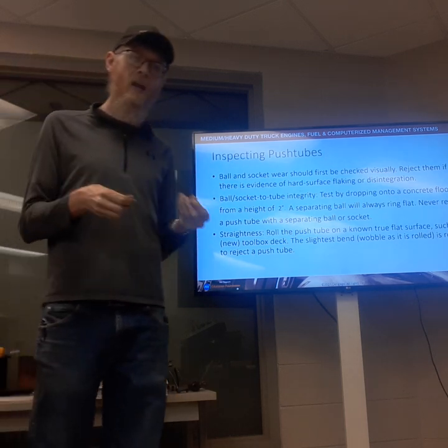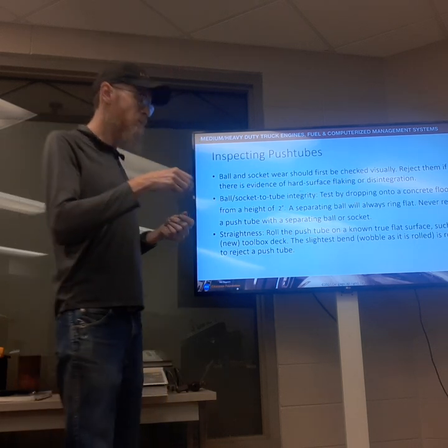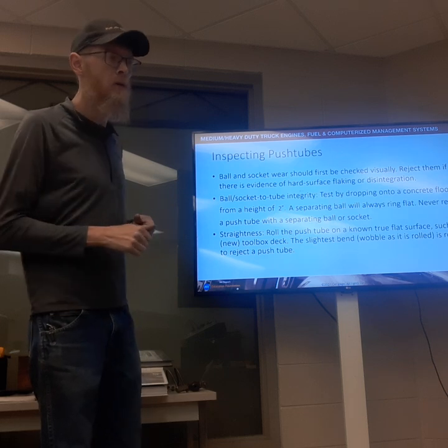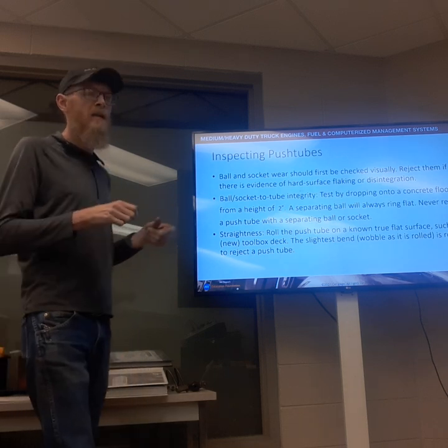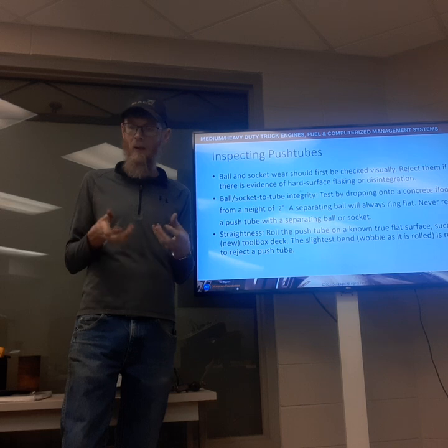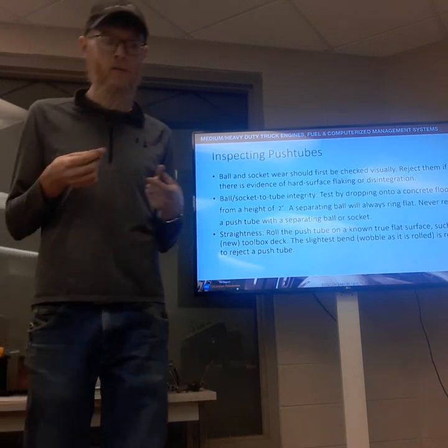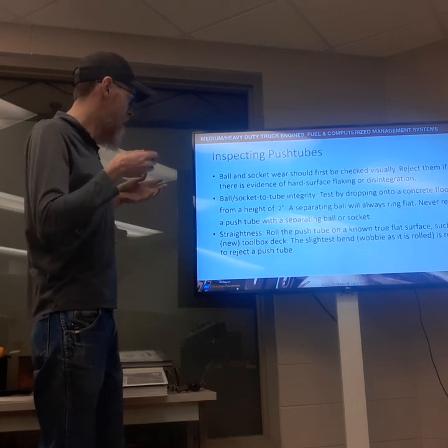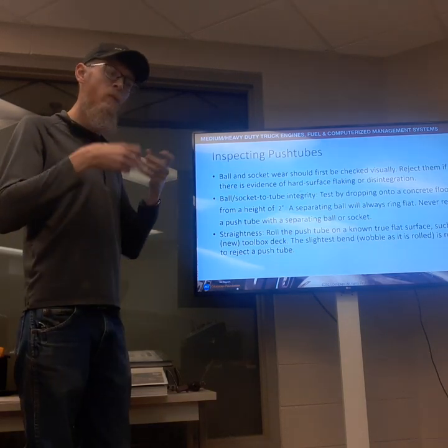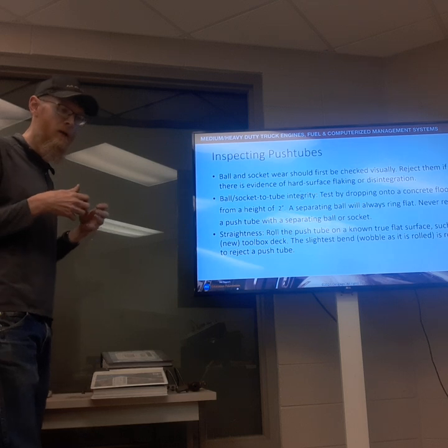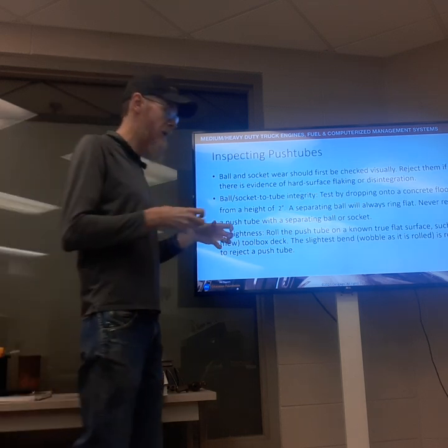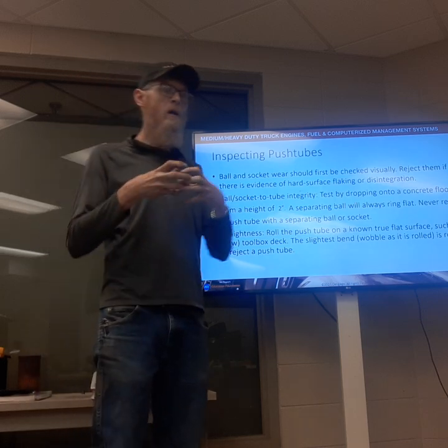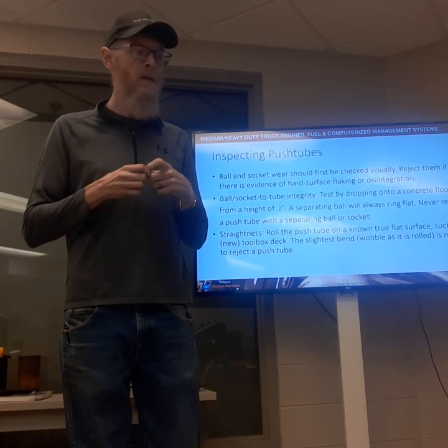Usually, if we do have damage from misadjusted components or lack of lube oil, it's pretty obvious when there's damage to these parts, whether it be through heat or friction or both. The damage is going to be rather obvious. Usually when we're looking at machined surfaces like this that move, there shouldn't be any wear patterns that you can catch with a fingernail.